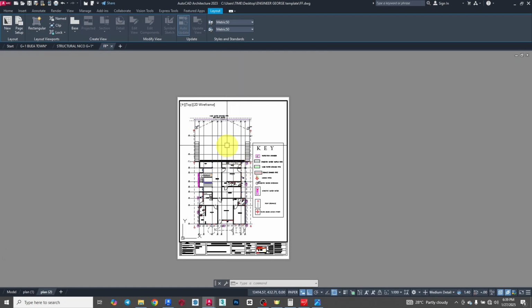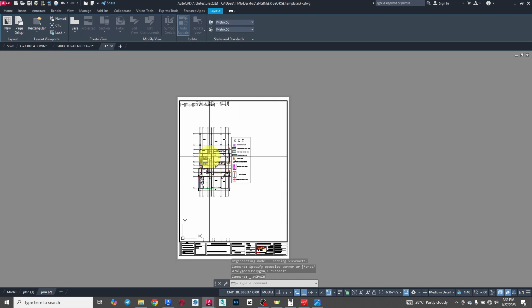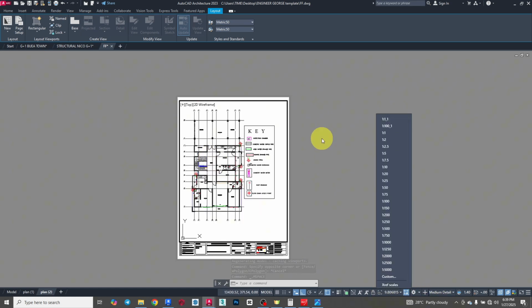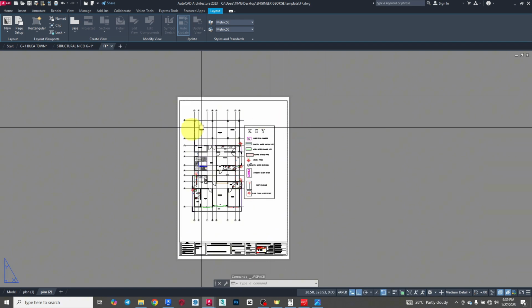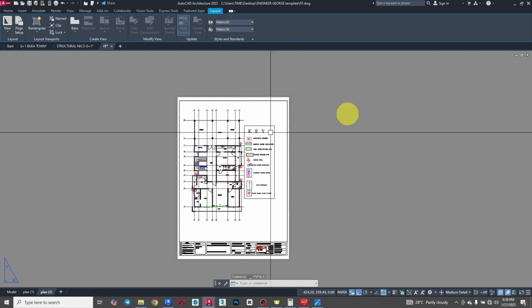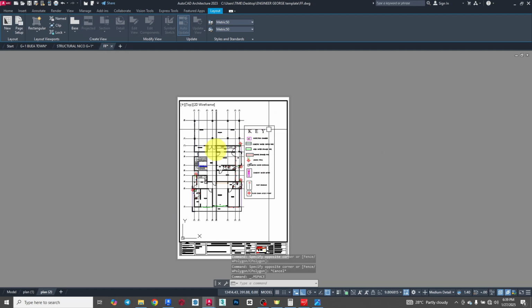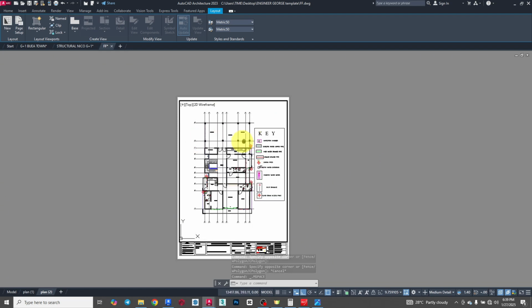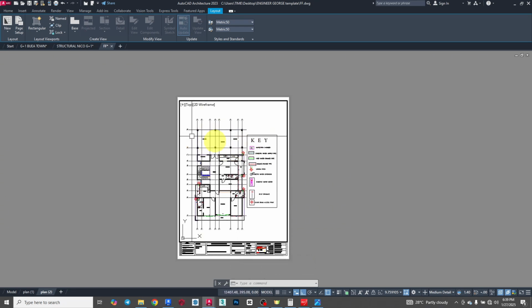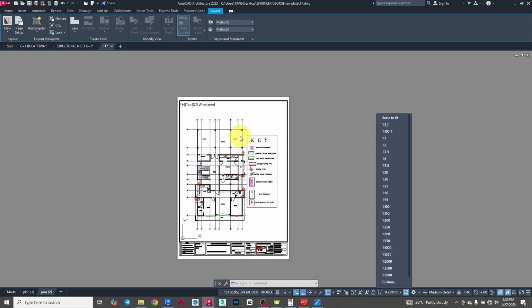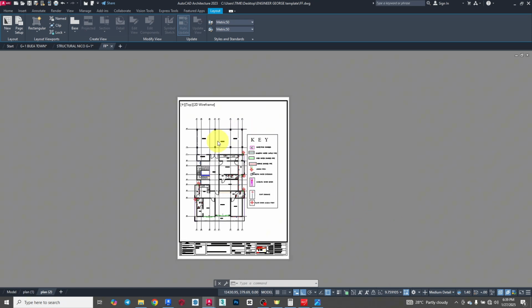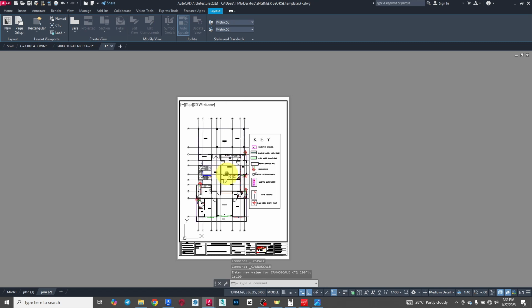You want to probably plot in another drawing that you have, and you check the scale down here. Remember I said I double click outside when I want to go out of this model space, and when I want to come into the model space, I double click inside this white space. So there I can have my drawings well fitted like that. While I'm staying in the model space, I can then change my drawing scale. Now this is what I want. Once your scale is all set, you can pan it to fit well on that sheet, and then double click outside.